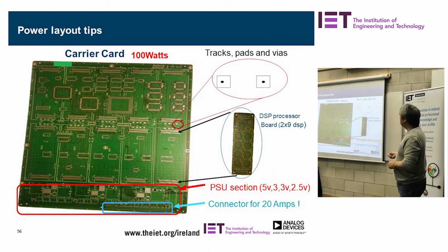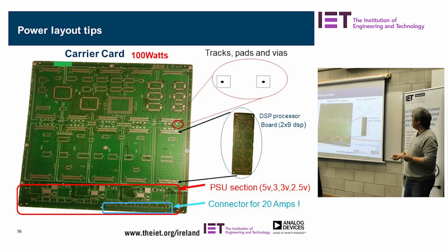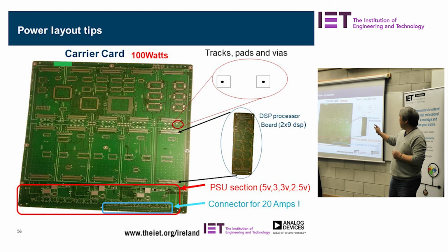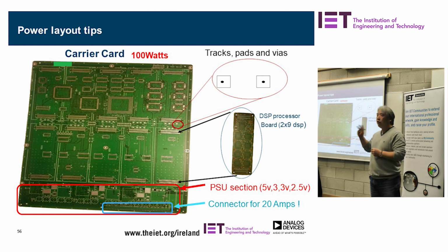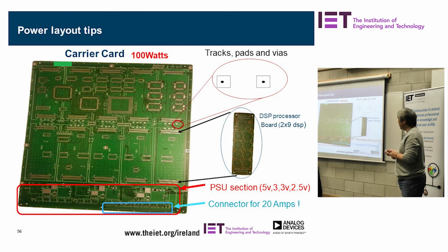All those connectors as well, make sure there are enough pins to handle the current capability. So in the design of this, I always say you need to follow through. You need to work with the layout guy. Don't fire and forget, okay? When you fire and forget, you come back to the board and nothing will work. You need to follow through, even for routine layout. I spent about a whole month with him laying out a board, even though he specialized in layout. I'm a design engineer, I'm not responsible for layout, but I had to supervise him doing the layout in order to get it right the first time.